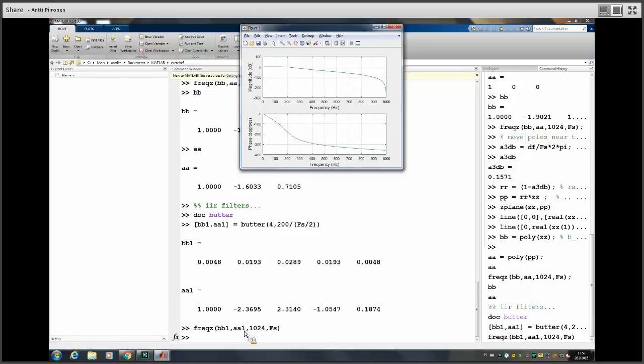Then next is the passband ripple. Butterworth actually has 0, but it doesn't actually matter. I'll just mark it 3 here, 3 dB. Maybe it uses it to calculate that one as a 3 dB point. And then stop band attenuation, for example, at 80 dB. Order number 12, order filter. And let's see, WN was